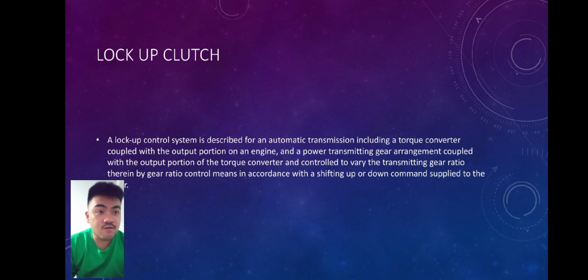The fluid used to control the torque converter lockup is also used to remove heat from the converter and transfer it to the engine cooling system through the heat exchanger in the radiator. Control of the hydraulic fluid to the converter is accomplished by the relay valve and signal valve. Both valves are spring loaded to a position which leaves the clutch in a disengaged position.